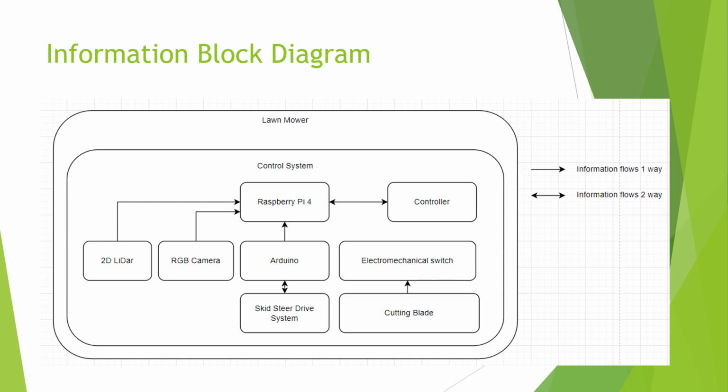This doesn't work perfectly, right? Because the ground is lawn. So if it skids or it skips or anything happens, we've lost some of that information about the encoder position. It's not exactly mapping the location of the mower because the wheels skipped around, so we've got more counts than we have rotation. So anyways, this is the overarching thing, right?